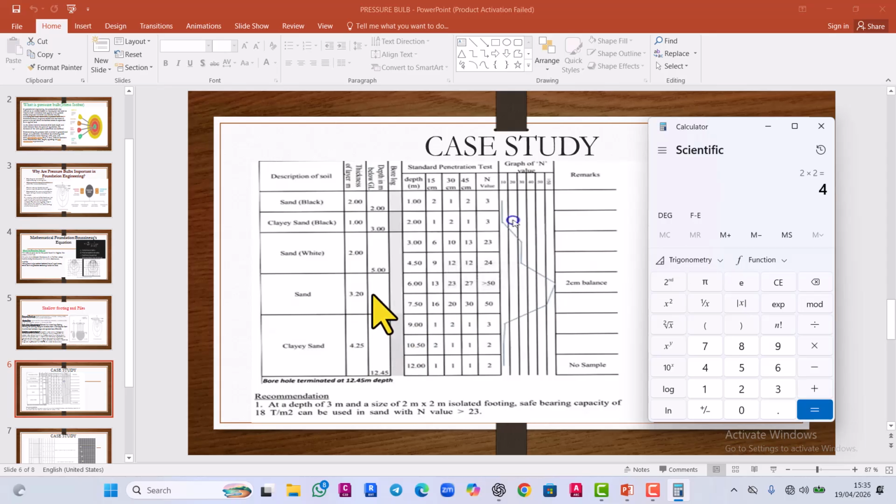But then let's say we are using 2, as the geotechnical engineer has specified. Let's say we now ignore the instruction of maintaining 2 by 2 meter. We now want to maintain 3 meter by 3 meter. And when we do that, we have 3 by 2, we are going to have 6. And that 6 falls within the clay sand with a bad soil.